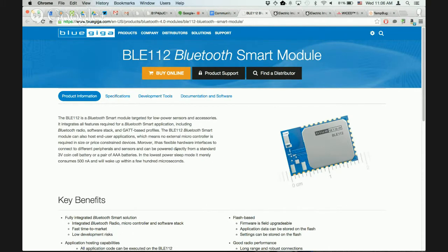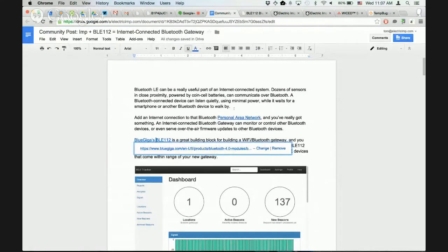And we've done a Squirrel port of bglib, so that if you hook up a UART to a BLE 112 to the imp, and you put this class in, and you run the stock bglib BGAPI image on the BLE 112, you can do all the things you could have done with the bglib C library. So we kind of cooked up a little example with that.